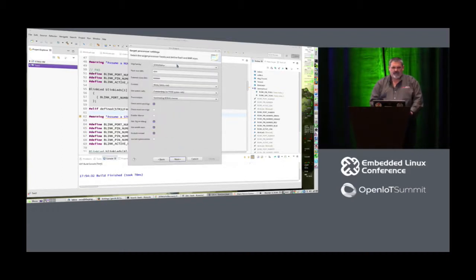And then we'll specify what kind of processor we're using. So they have all of the Cortex-M processors for that particular manufacturer already defined. So we picked the one that we happen to be using, and I think mine's a 407. We have how much flash we have. It turns out that my board doesn't have 1024. It's only got 512 kbytes worth of flash. The external clock is, I think, still running at 80 megahertz. And we have here a blinky LED content, or we can add an empty project.